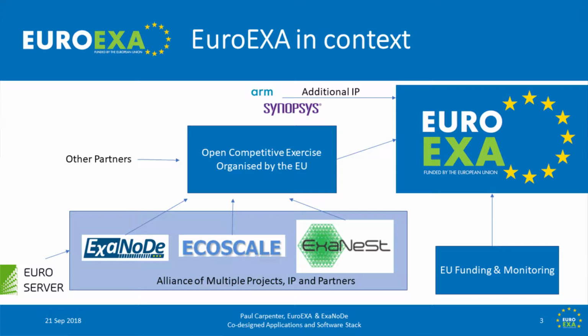ExaNoDe is concentrating on the node architecture, so it brings MCM integration, it brings runtime systems and things in the node. EcoScale is FPGA offloading with an OpenCL programming model, and ExaNest, the title comes from the fact that it focuses on the networking and the storage.